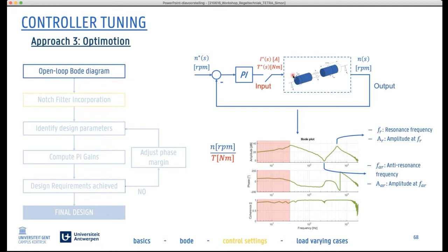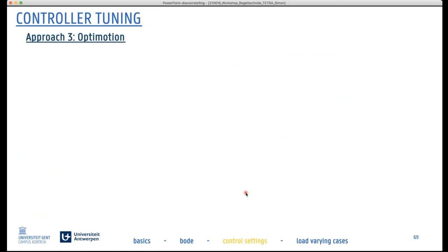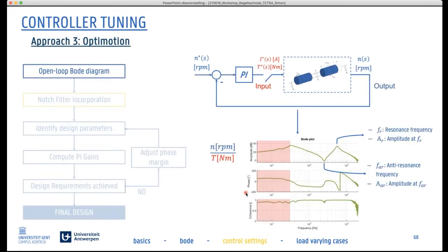In positioning applications, it's very typical to have a motor inertia, a flexible coupling of some sort, and then a load inertia, and then you get a bode characteristic like that, with its pronounced anti-resonance and pronounced resonance. Based on those parameters, you can actually design not only a controller, but also a filter. And that's quite interesting. Why would we take that resonance frequency for granted? And why wouldn't we apply a technique where we filter out that frequency?